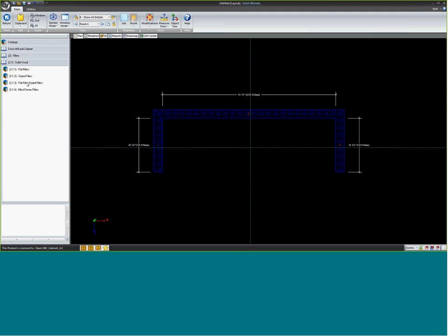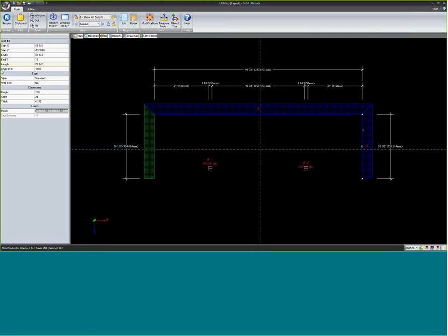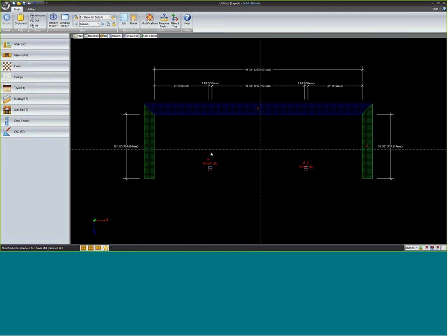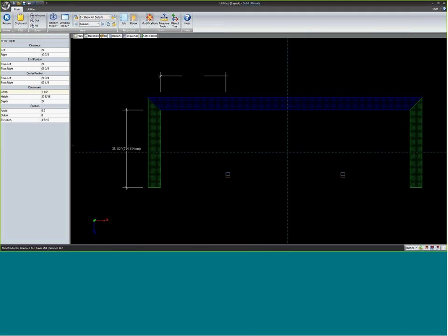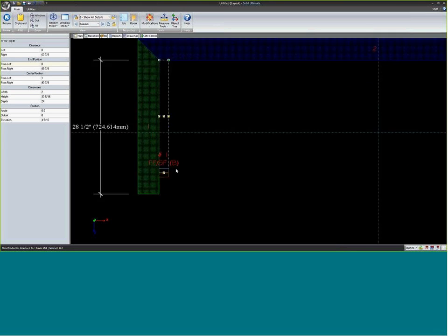For instance, I'll come in here and pick a combo filler, and let's pick base flat filler, styled filler combos. I'm going to right-click and copy that one over to here. Let me change my walls to wall ends also, since we want to do that as often as we can. Now, on a filler, if I only want 1 inch of it to show, but I want another inch worth of scribe, I can make that 2 inches wide, for instance. Let's make this one 2 inches wide. Now I take that filler and my end position. If I just go like that, I'm 2 inches wide.